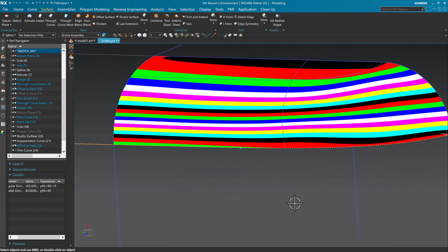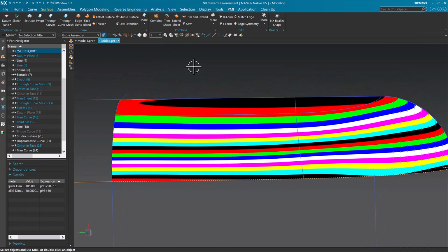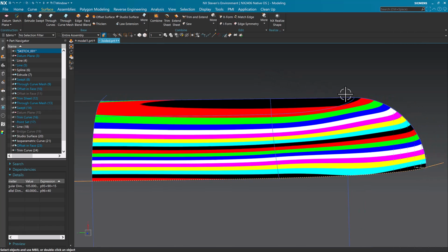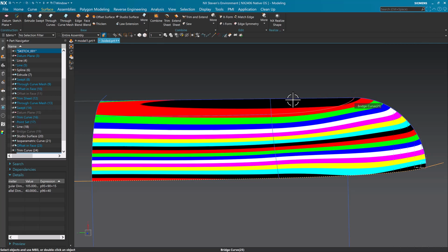Now, if I could, I would add the slightest bit of crown to this. When I say slightest, I mean, we're talking absolutely minuscule. Maybe a 1,000, 2,000, 5,000 radius, depending on the size of this. And then, do the same thing, or maybe just a conic that's almost perfectly flat, right, through those 2 points, like bring this point in just a hair, just to get a slight bit of acceleration. And then do the same thing with this, maybe use a conic to try to get that shape and mimic it as closely as possible.